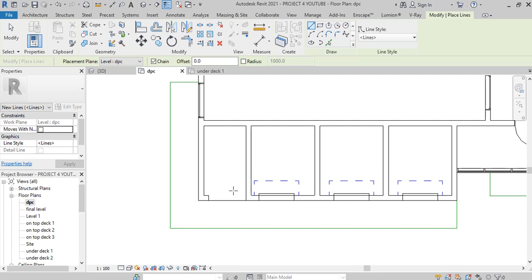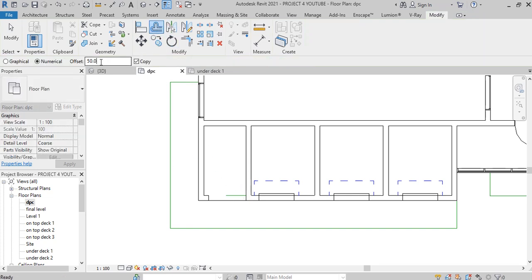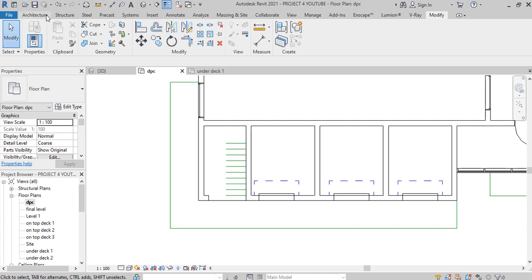First of all, I'm going to start from this point, so I can go out 1800. We are likely getting 900 on each side of the run. In this case, because of the middle partition, I'm going to be taking 850 from this point, and then next I pick offset, and I'm going to offset maybe say 250 millimeters. Then I start from this point.